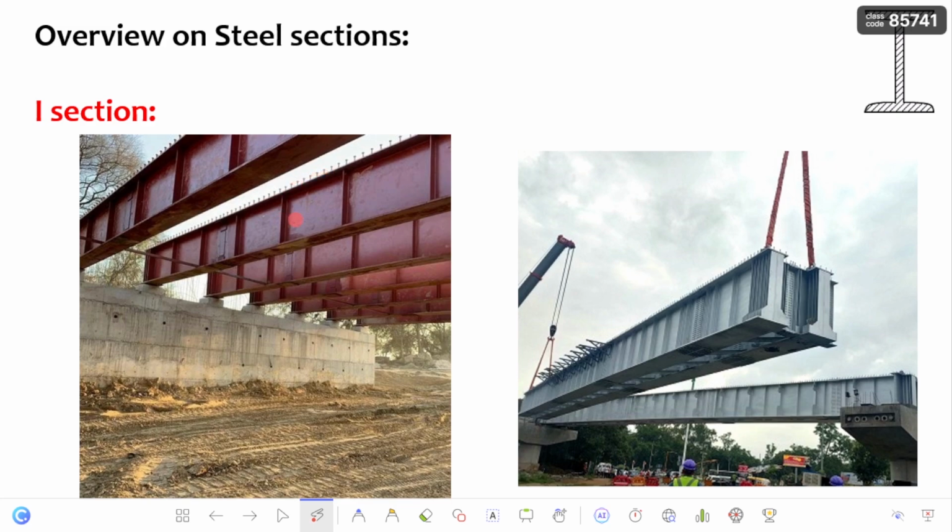These plate girders are basically preferred when there is a large span and heavier loads are coming onto the structure. They are used in bridges and also launching girders. And here you can see a picture related to the composite steel girder. This composite steel girder is basically preferred for higher spans, like greater than 50 meters. In metro construction, when the spans are 50 meters or more, they prefer this steel girder, and on this steel girder they cast a deck slab. We can call it a composite steel girder. This is regarding the applications of the I section.